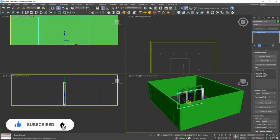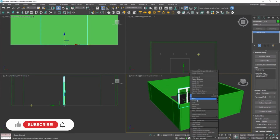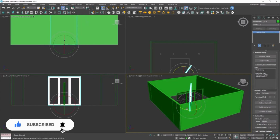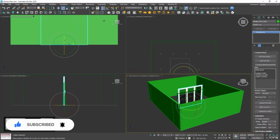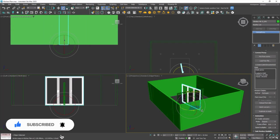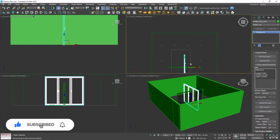And now we want to rotate them. So if I select our doors and rotate, you can see it's not actually snapping. So let's undo that, and we can go up here and turn on angle snaps, or you can press A. And now notice that we can rotate to 90 degrees. So over in the top view, let's move these into position.